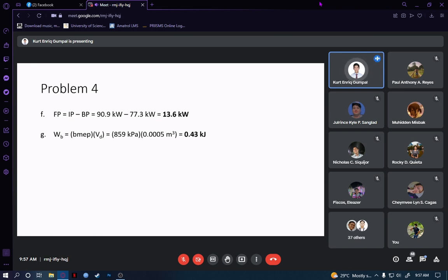Okay, right? Your heat is equivalent to your effective pressure times your volume. Since it is per cylinder, we use the volume displacement per cylinder that we got, which is 0.0005. So 859 times that volume is equivalent to 0.43 kilojoules.